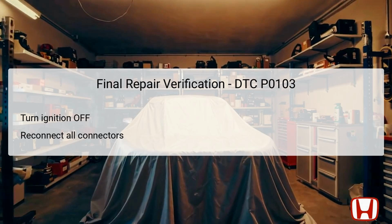After completing this process, turn the ignition back to the on position and carry out the idle learn procedure as specified in the service manual. Finally, check for any pending or confirmed DTCs once again to ensure that DTC P0103 does not resurface, which would indicate a continued issue that needs to be addressed.